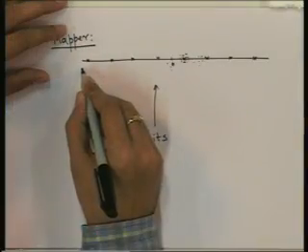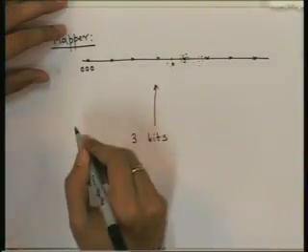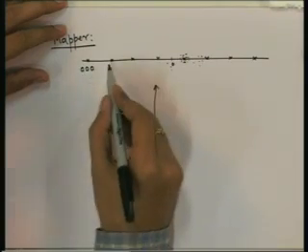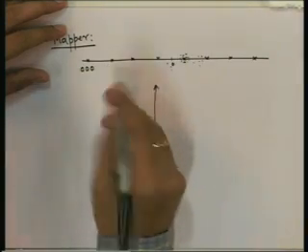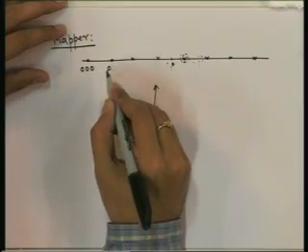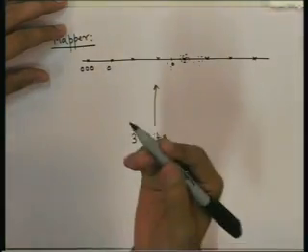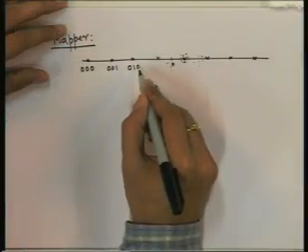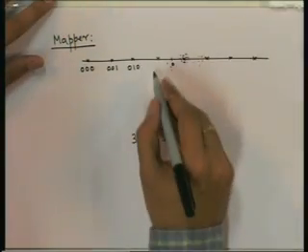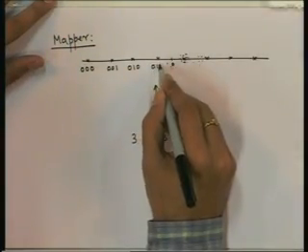So, we should try to see that the difference of bits between the neighboring points is minimized. There should be very little difference between the neighboring points. This is one particular way of doing it, and it is called gray coding. Take 000 here, then there should be a 1-bit difference between any 2 consecutive points. Then most of the times there will be only 1 bit error when there is a symbol error. So, there is a 1-bit difference here, then a 1-bit difference here, and then here also a 1-bit difference.